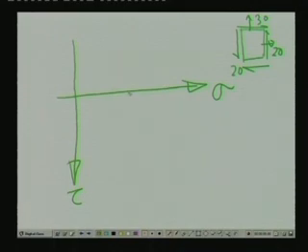First of all, we locate the plane where the normal stress is 20 and the shearing stress is 20, so we go in this direction as 20 and the positive shear stress as 20.